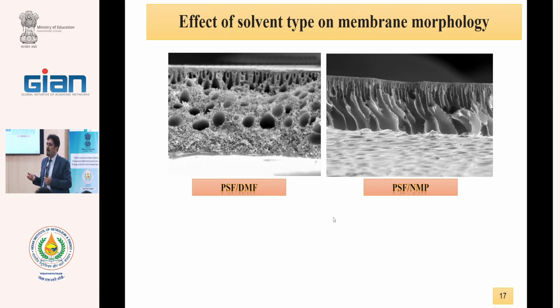Also, in fabrication of most TFC membranes for gas separation and RO, after preparation of the membrane, we coat a protective layer on the membrane surface for reducing defects in modulation. When we make the module and produce the envelope, the surface of the membrane can be harmed and can develop defects.